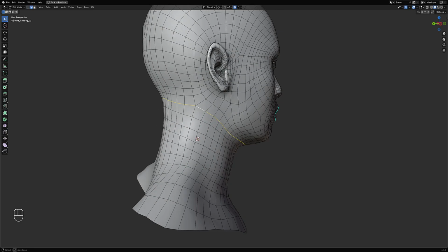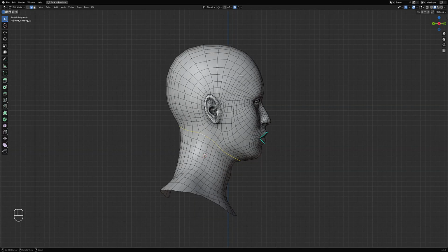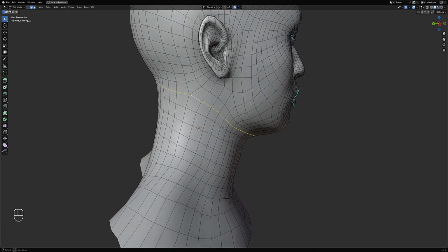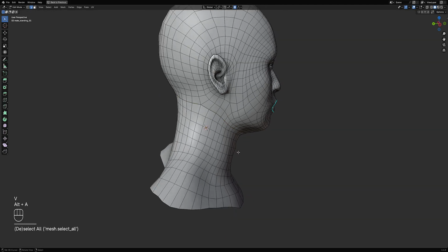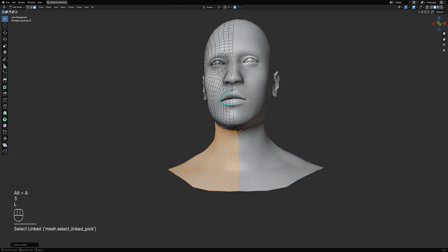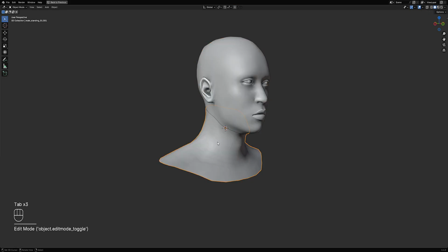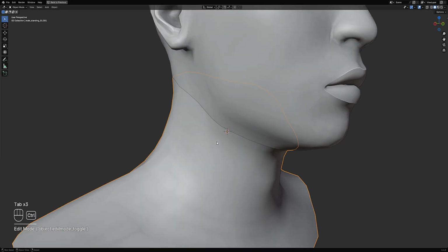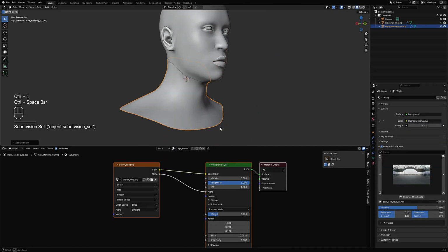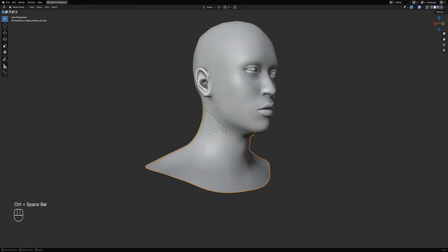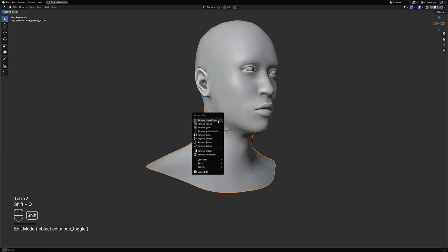So first off, I'm going to extract a part of the model and then use it for the organic suit, and then we're going to model something off from the face and then continue layering the effects after that. So V to split, and then L to select all the faces here, and then separate by selection. So I'm going to add a single subdivision modifier, and then in the settings I'm going to copy all modifiers.